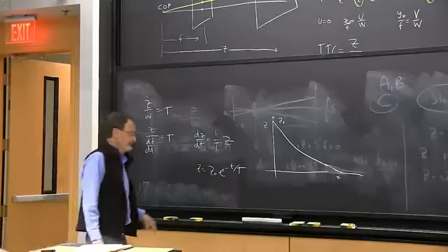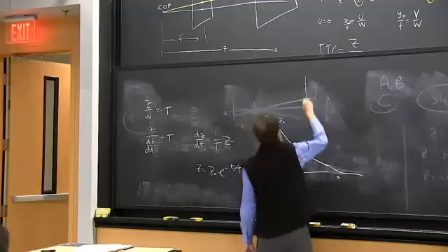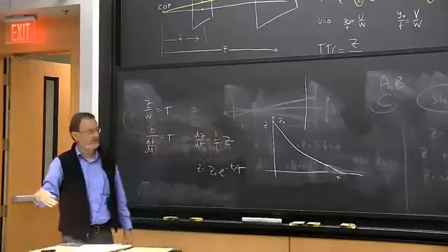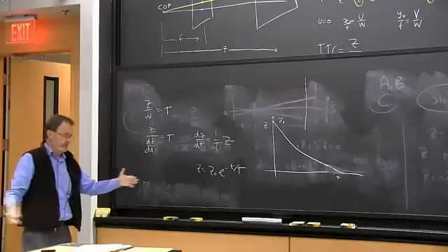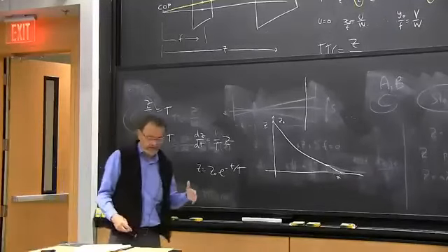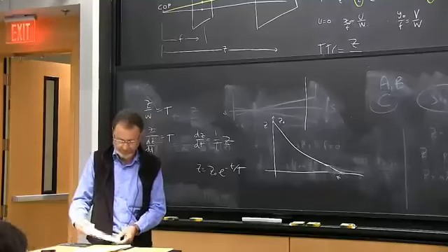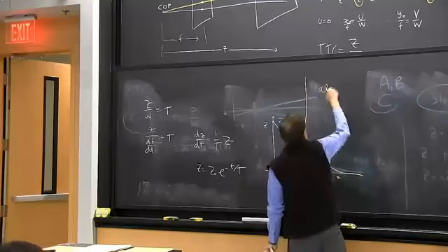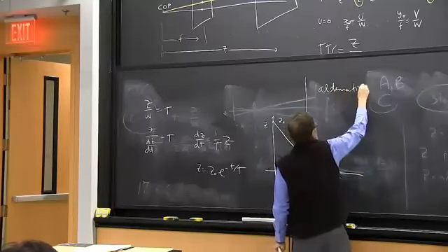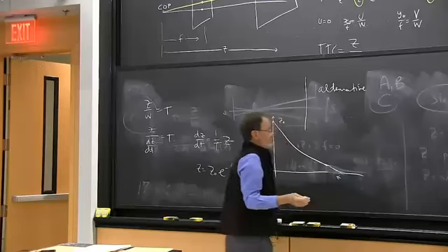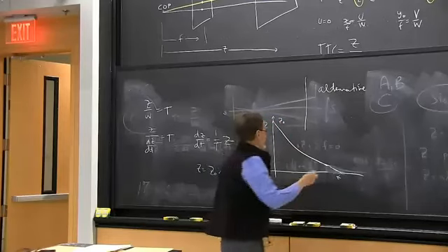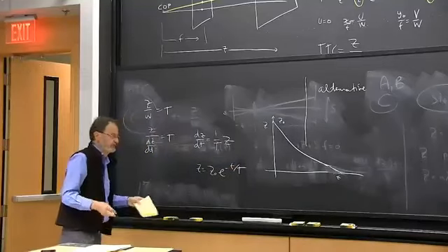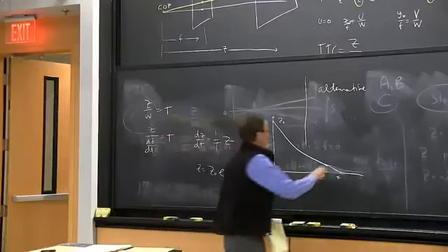Just for fun, we can compare this with a more traditional approach. So a more traditional approach would be, we run the engine at its rated speed, and we decelerate, and we only turn it on at the time where we need to turn it on so that we don't crash into the surface. Now that method requires that we know the distance to the surface and we know the velocity. So we have to know a lot of stuff. Where with the time to contact control, we don't. You just keep the time to contact constant.